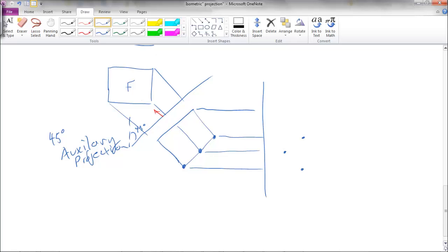And then on the other side of that point we've just taken, it's another hidden corner, which you can't see from this view, but because of our other two orthogonal views from earlier, we do know it's there, so we can take that and place that there. Now we know it's all straight edges connecting this, so we just go in and fill this square in. So that's sort of looking at the bottom of our cube.